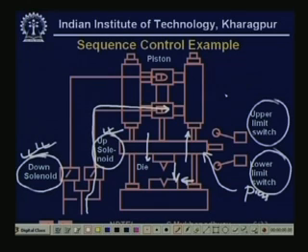So, this is a typical example of a sequence control problem, where we are interested in only, see, the system is, everything is analog if you look fine enough. So, obviously the piston cannot, the system cannot instantaneously come down from the up to the down state. But what we mean is that for the sequence control of this system, we are not interested to know the intermediate states.